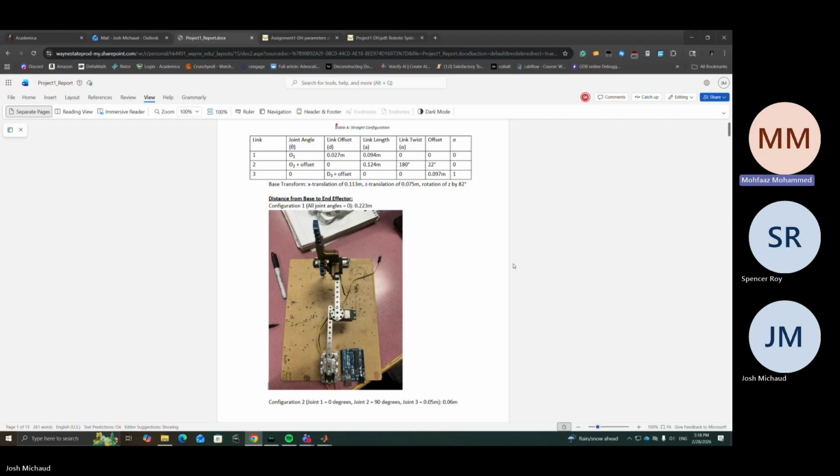So we are here with a three-link robot which we created for our demonstration of robot kinematics. We use different types of DH mounting over here. As you can see, we have a three-link robot with two revolute joints and one prismatic joint. We have a base frame on this board. We assigned all the required coordinate frames for this particular robot. By the assignment of these coordinate frames, we also got a DH table for this robot. And since this robot has three joints, therefore we have three rows over here. The first two rows represent the two revolute joints, and the third row represents a prismatic joint.